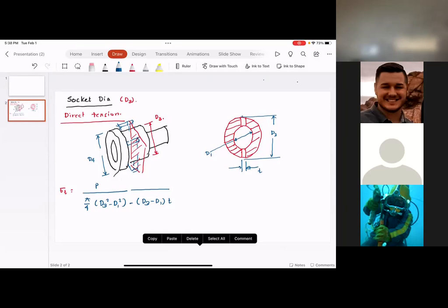When we talk about bending failure, there are 2 types of failures that we have in mind: failure because of yielding and failure because of fracture. When we look at the failure in bending, we assume that the cotter has exceeded its yield stress, which means it has deformed. But recognize that the cotter might not have sheared off. Basically, it might not have failed, because there's an upper yield point, a lower yield point, and then there is a failure stress.